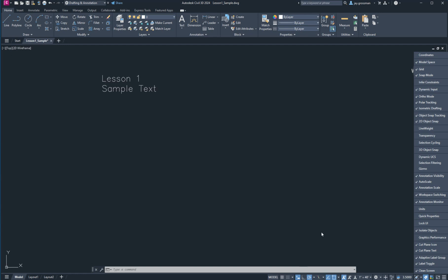That looks like that for dynamic input. We'll talk a little bit more later about what dynamic input means. So there's either absolute input or there's dynamic input. And dynamic is a relative reference from where you last were. Absolute is what it sounds like. It's an absolute coordinate system. So that's what dynamic does for us.